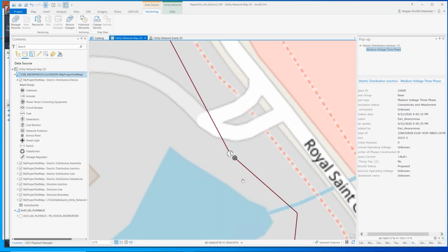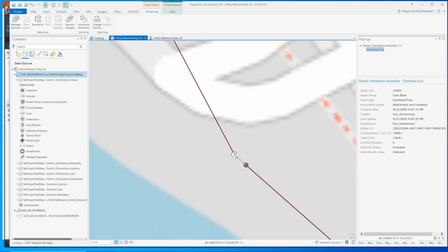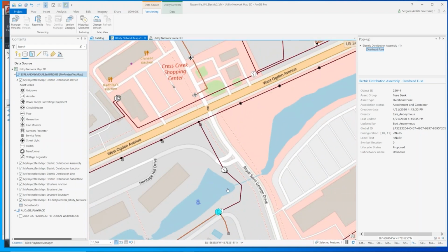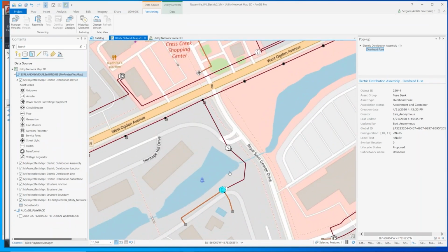So because we're in CAD that's civil surface aware, we can take that elevation into account whenever we do design. And all of our analysis takes that into account too. If you do sag on elevated poles, or you do cable pulling tensions on different elevation vaults or whatnot, all of that is taken into account with the analysis.